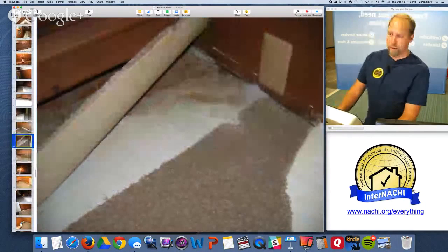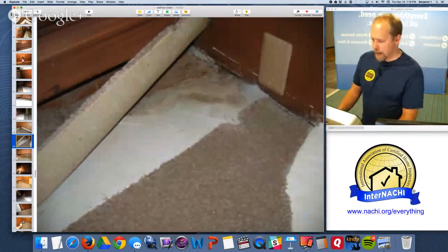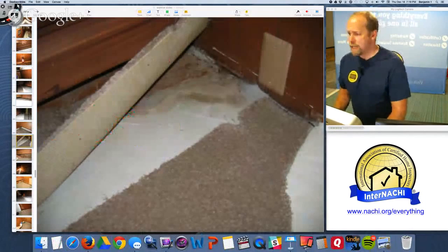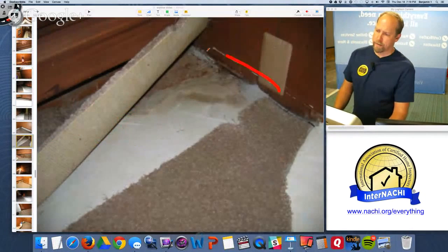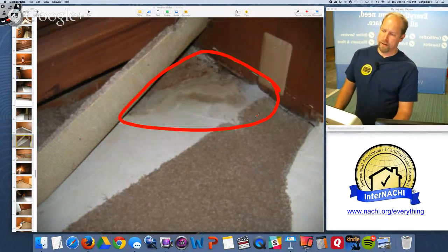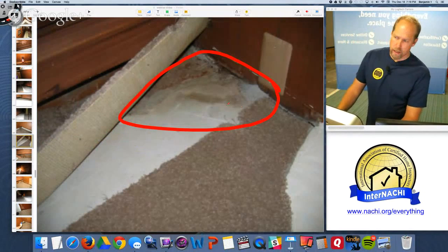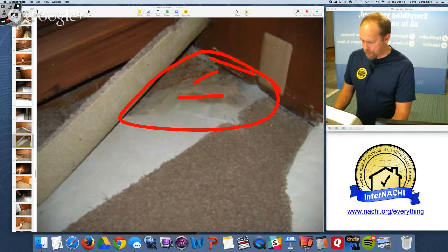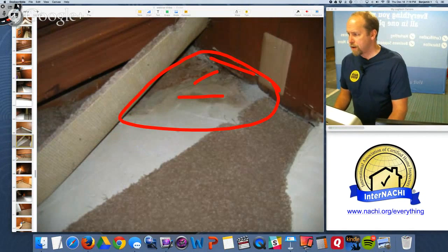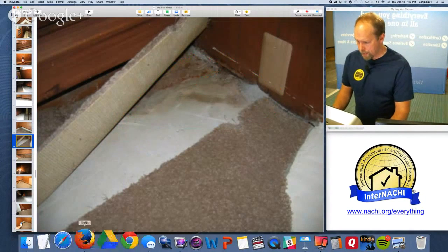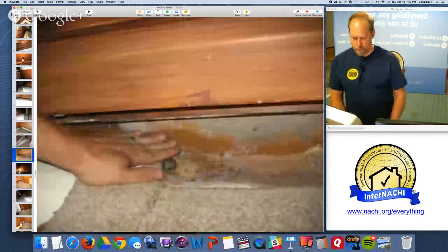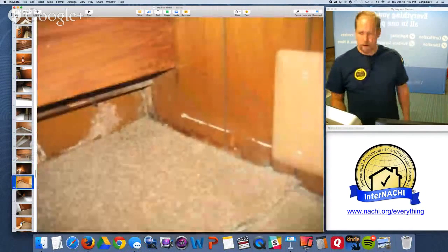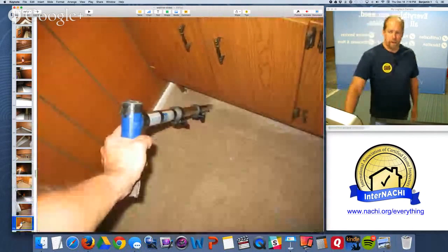But I'm going to use my moisture meter. When I can, I pull up the carpet so that nobody complains about it. I don't go crazy, but look, this is all wet. So this is a wet carpet, wet stains, moisture. So it's a good thing I have a digital camera because it'd be kind of difficult to explain what I see. It's actually wet to the touch. Best tool an inspector can have is your hand. So we have water problems in the house down in the basement.